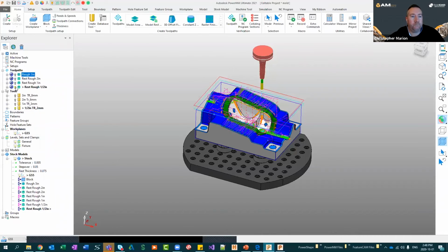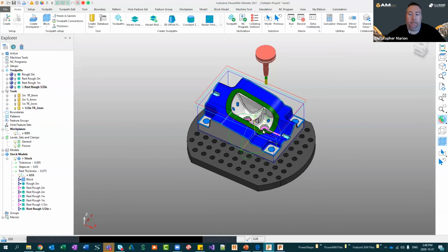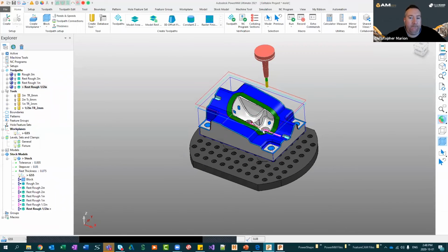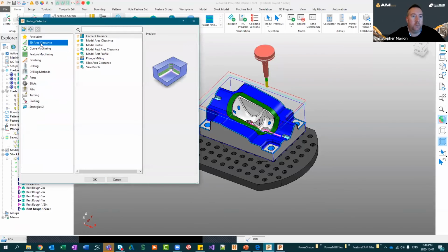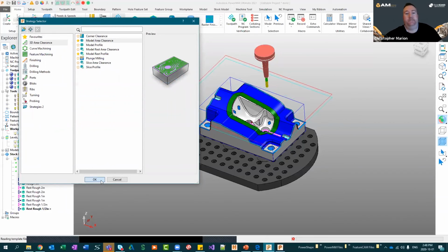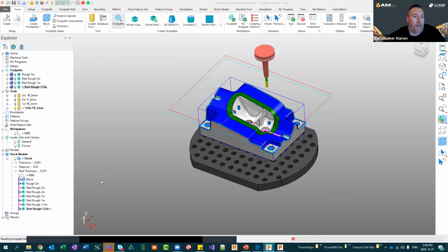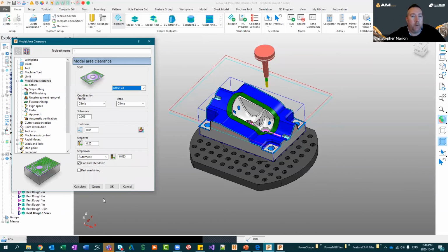That's very insightful. Thank you. Does PowerMill have an adaptive roughing toolpath? Yeah, there's actually two. So the nice thing about the collaboration between developers on the Autodesk side is the fact that Delcam has their own patented adaptive roughing. That would be Vortex, but there's also, if I just pop open here real quick, the one that came from HSM or Fusion, which is the other adaptive rougher, which I find I kind of like a little bit.